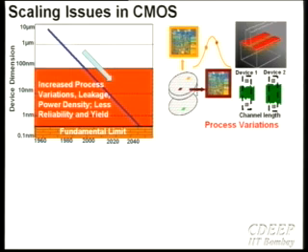So people have been looking at various ways of doing nominal design, but along with the nominal design, considering different error resilient techniques. By the way, some of these are going to be very important in memories, not so much maybe in logic, but certainly very much in memories where matching transistors are required. So from a mixed signal point of view, matching turns out to be important.